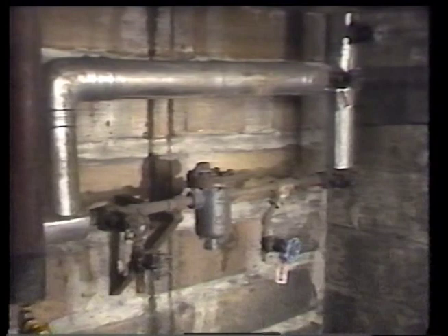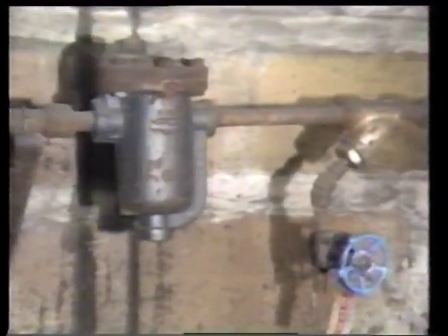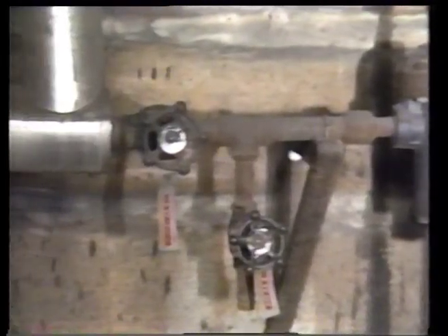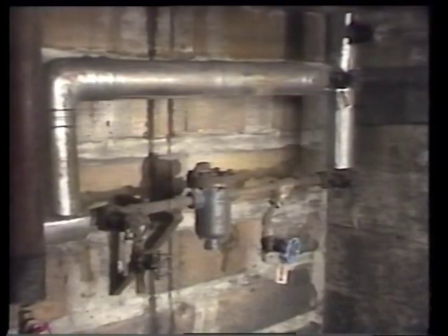Also, in order to determine if there's something wrong with a particular trap, you must know whether the rest of the trapping system, that is, the pipes, strainers, and valves, are working properly. A failure of any one of these components could make the trap look like it needs repair or replacement, when in fact there's nothing really wrong with it. In this segment, we'll be talking about ways to ensure that the trap system is working properly, and we'll discuss specific techniques for troubleshooting steam traps. Techniques based on sight and sound.